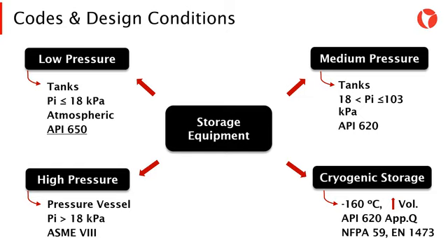A good comparison could be made regarding the pressure level to which they can operate. Storage tanks designed according to the API 650 code are also known as atmospheric or low pressure tanks, since they can only operate with internal pressures below 17 kilopascals.